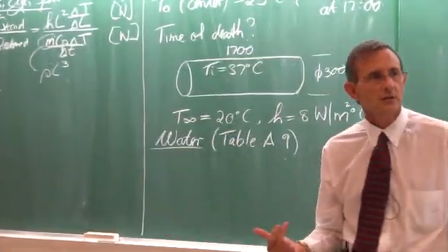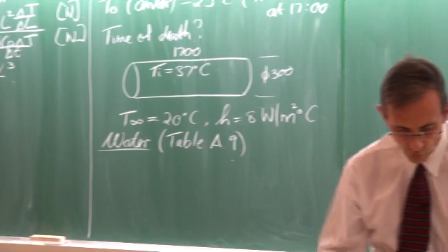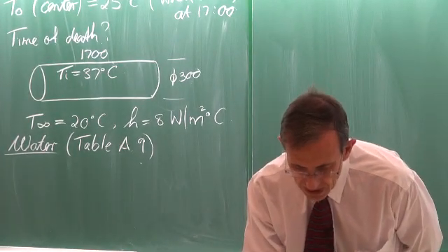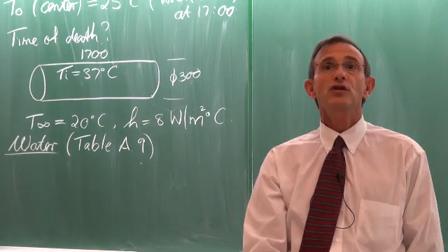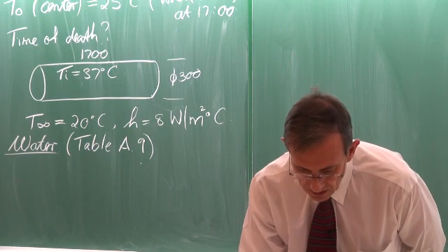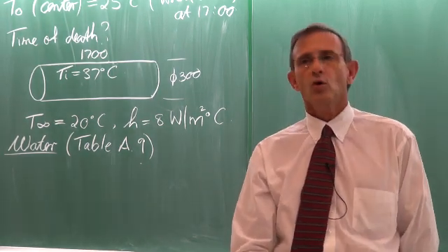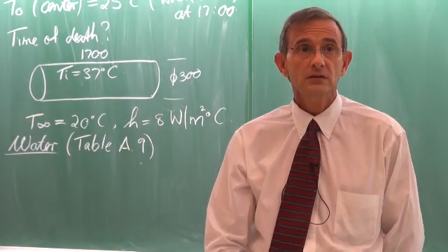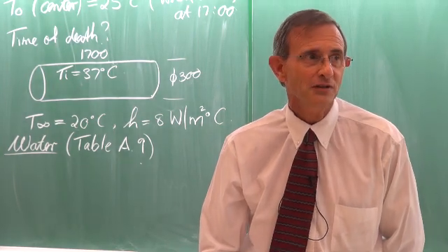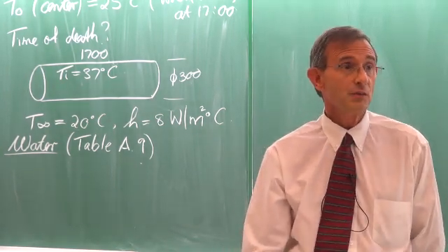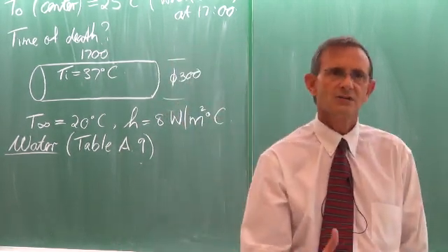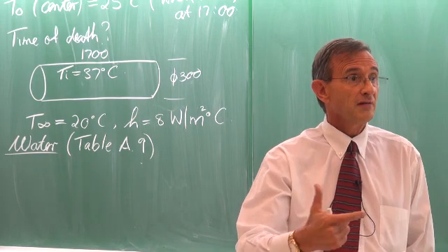Okay, what temperature do you suggest we use? If we, for example, look at 20 degrees Celsius, you will see that the thermal conductivity of water would be equal to 0.598. If you would use it at 50 degrees, it would be 0.644. So it's different, but if you look carefully, you will see it is not that much different. So it is dependent on temperature, but it's not a strong function of temperature. And the same with density, you'll see the change would be very, very small.